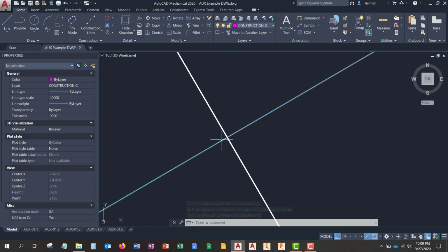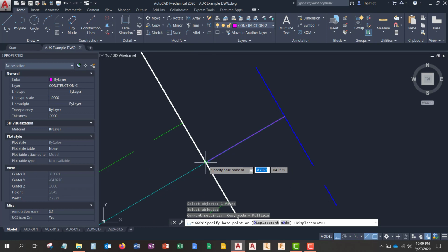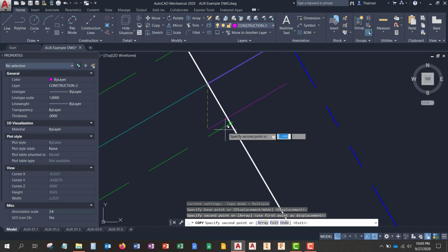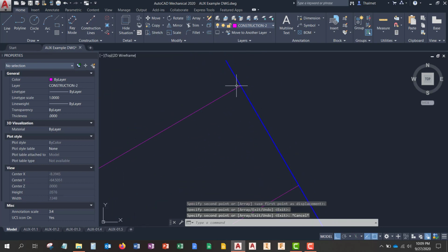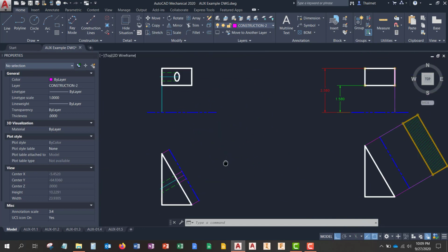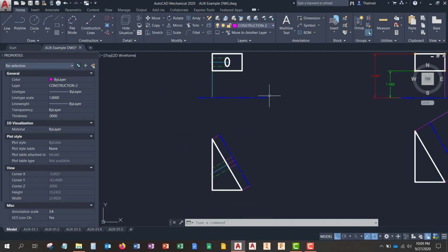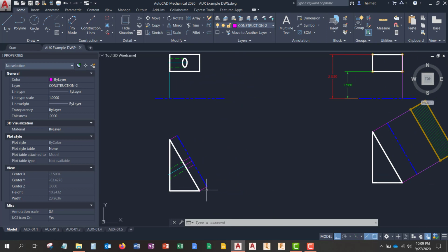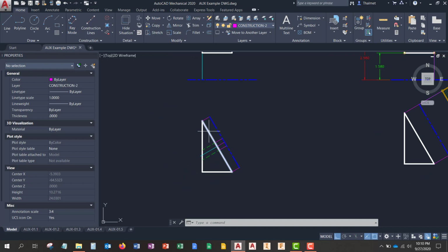Check our center line here. Perfect. Okay. Now, going back in here, grab that, grab that. Okay. Double check those just to be sure. Perfect. So anytime we have a cutout, a hole, anything that breaks up that surface of the auxiliary, we want to be sure and account for it on our auxiliary view.